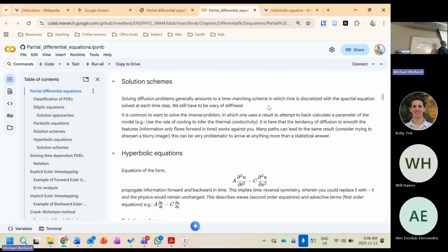And if you want the easy analogy to that, just take it a little bit farther. Your final time is going to be flat everywhere, and now you have absolutely no clue. This would be the result of a pulse here with infinite thermal conductivity. This could also be the final state of a pulse here with a super slow thermal conductivity. And because it's a continuous thing, it has to dissipate that information. That's the nature of the parabolic equations. But that also is a big thorn in the side of any kind of inverse problems.